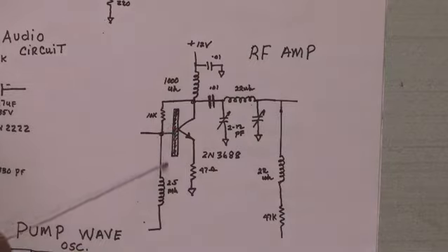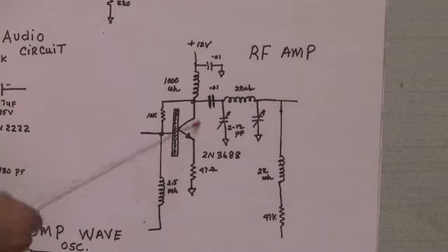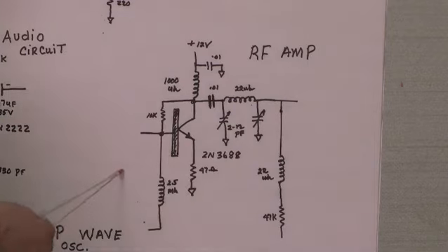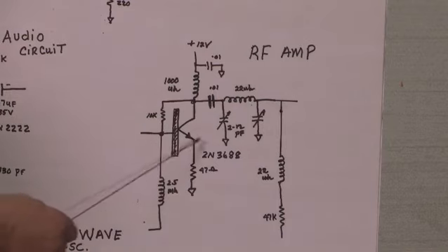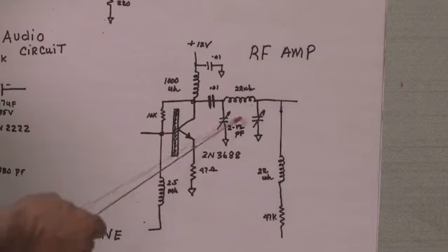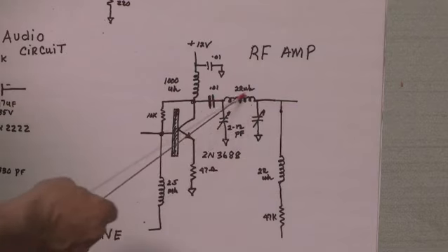And so this transistor here is very important because this is a regular RF transistor and it needs to have a heat sink on it, which I'll show you when I bring out the machine in a few minutes, and I'll point out what the components are. These are trimmable capacitors that adjust this pi network.